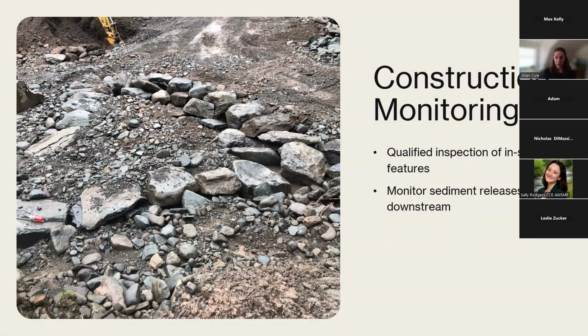Additionally, downstream areas should be monitored for excess sediment releases. So if the water coming from the project site is muddy or less clear than it is upstream, then the dewatering and erosion and sediment control devices should be checked and repaired or modified as needed.